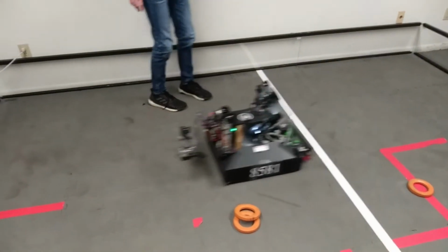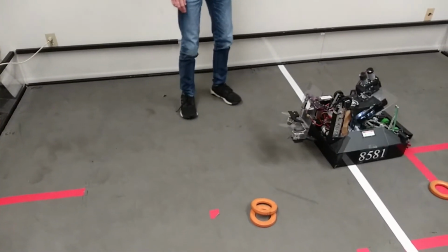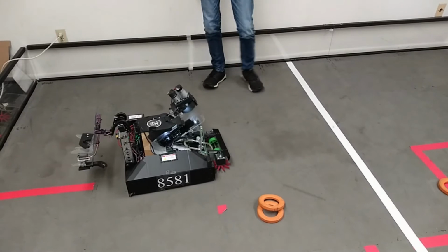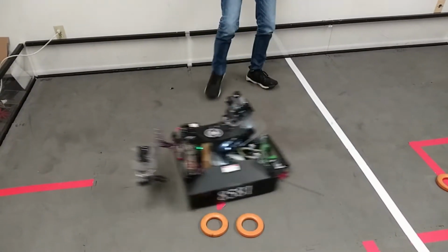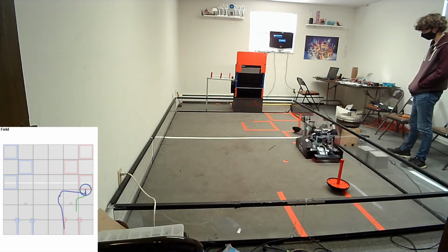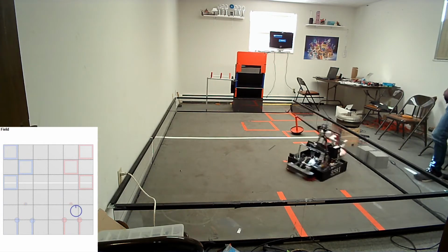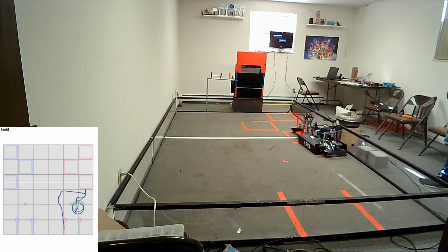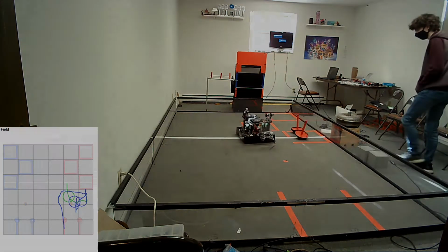In past years, we've had issues in autonomous making the robot drive in the exact same way all the time. To resolve this, we decided to use Roadrunner, a motion planning library maintained by Acme Robotics designed specifically for FTC. Roadrunner uses PID loops and motion profiling, and also takes into consideration the kinematics of the robot's drivetrain to help with consistent autonomous driving. It also helps us make more complex movements like turning and moving forward at the same time.